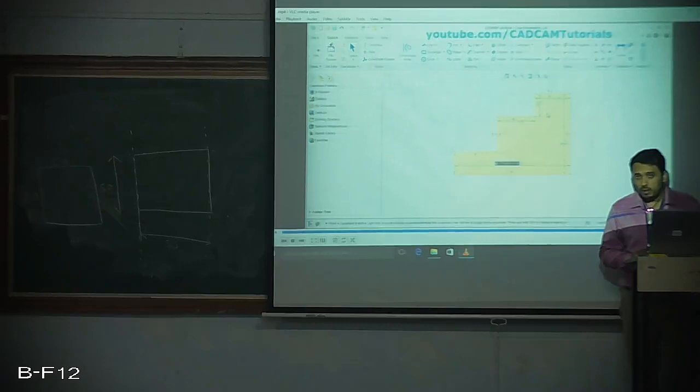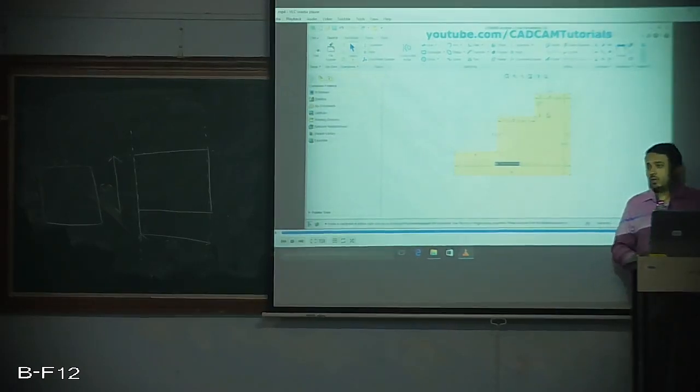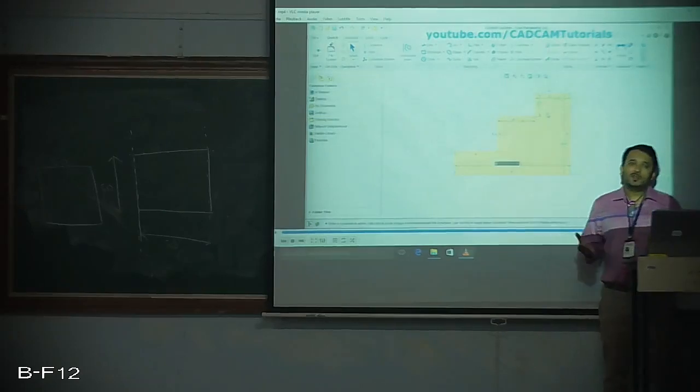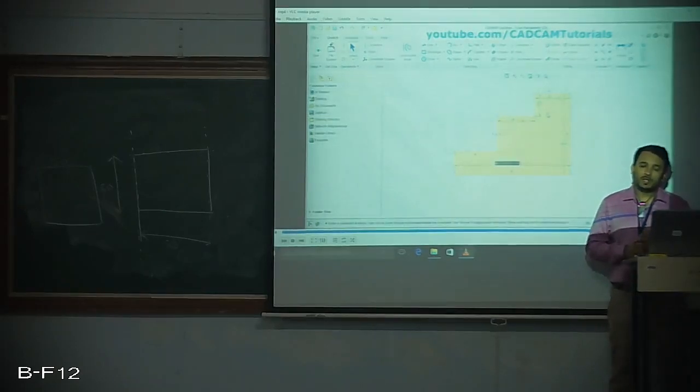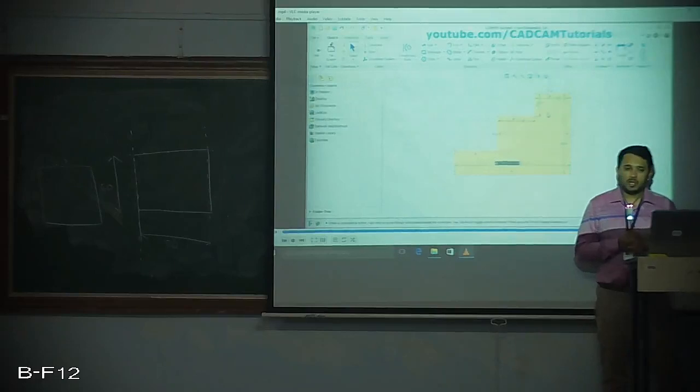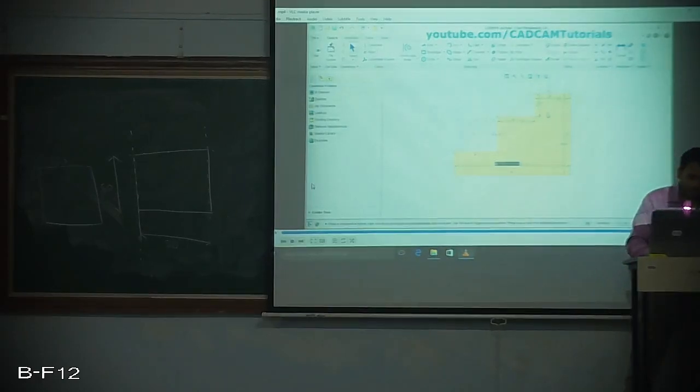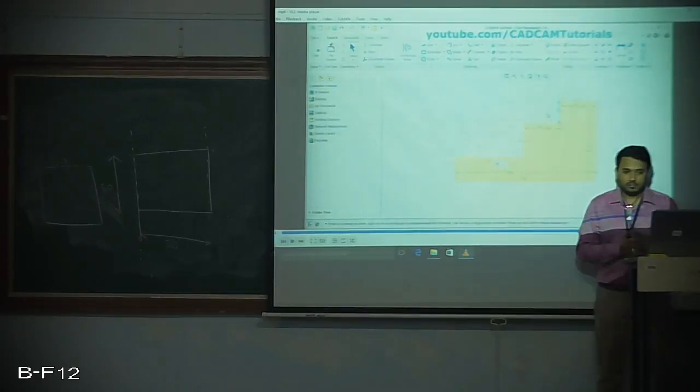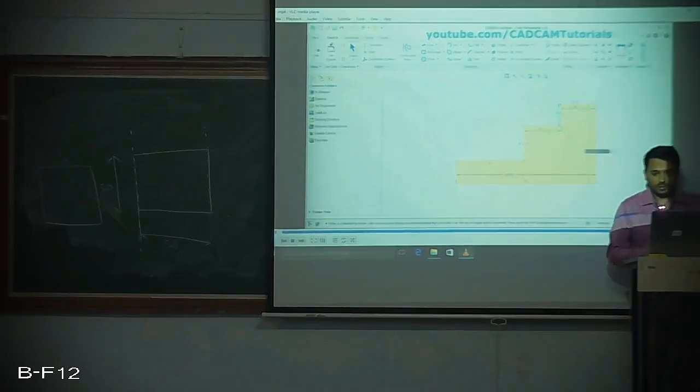So if you want to change the dimensions, you need to click on that particular line by using the normal, or the auto dimension in other software. When you click on the normal and click on the line, it shows that the sketch will be auto constrained, because it has taken the length of the previous parallel line. Hence you need to delete that constraint, then only we will be able to change those particular dimensions. See here, you can see that over here.